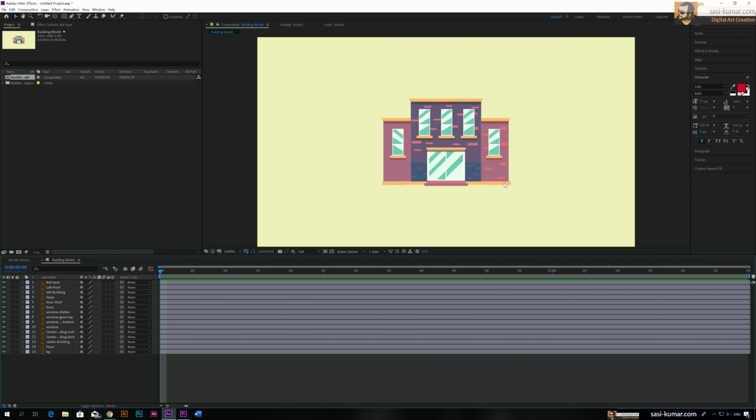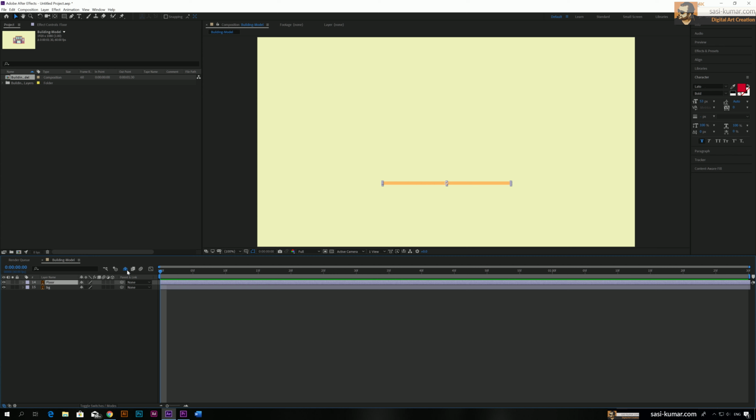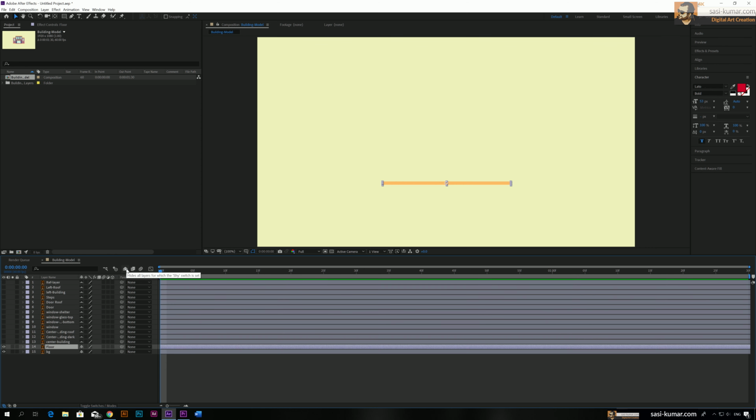First thing that I'm going to do is animate the flow, because that is the first animation you see on the screen. So I will keep only the flow. All the other layers I'm going to hide. All right guys, so let's select the flow. If you find these things distracting in this After Effects timeline, you can select all these things in here and click this one, the shy switch, which will hide the shy layers. So we will only see these two layers. We can go back just by clicking this one if you want to.